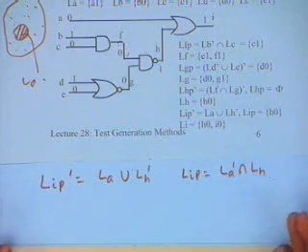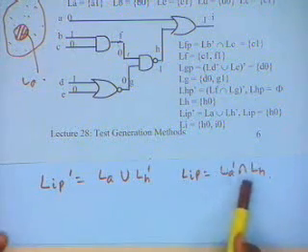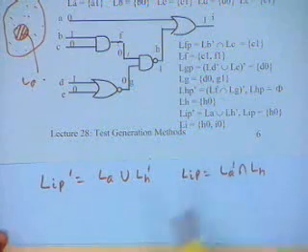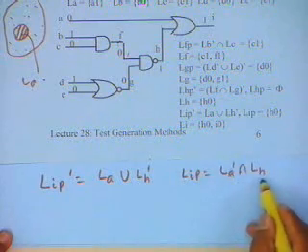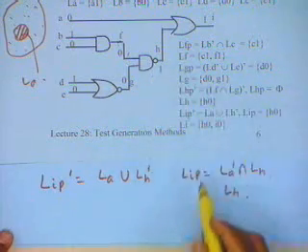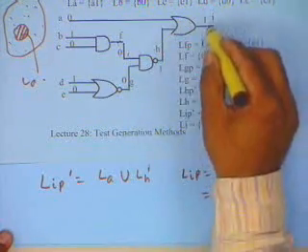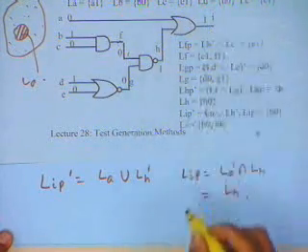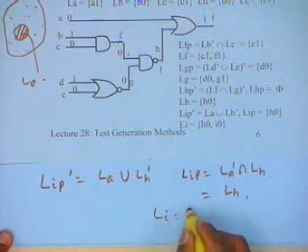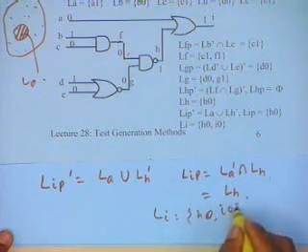Okay, you can also think in terms of the De Morgan's laws that you have studied for logic, or you can also think in terms of the set theory that you have studied in schools. So it's basically just replace the union by intersection and take the complement. So now I have LA complement intersection LH, and this is LH. LH was nothing but H0, and I can also detect the fault which gets generated at I itself. So LI would be H0, I0.